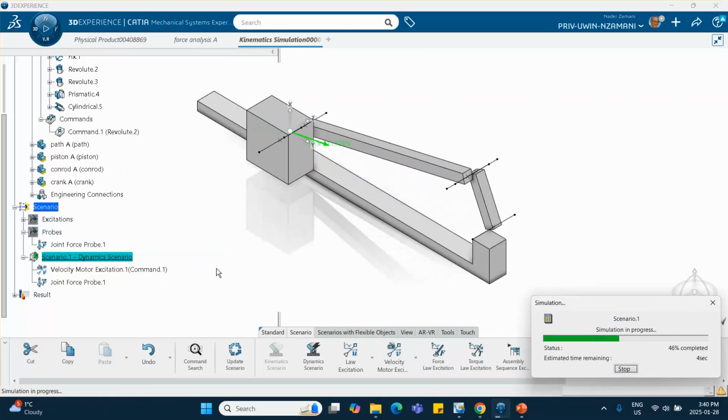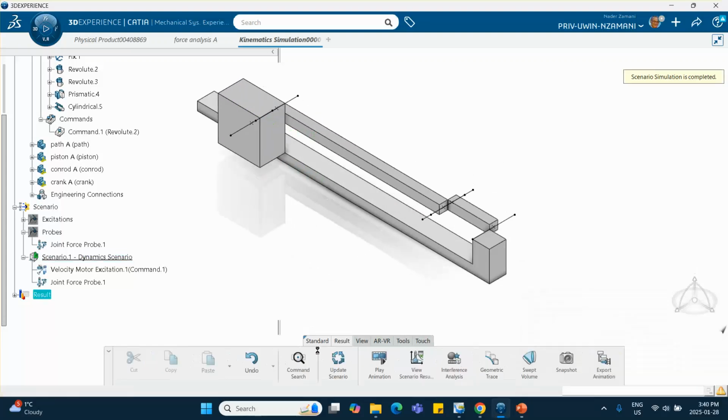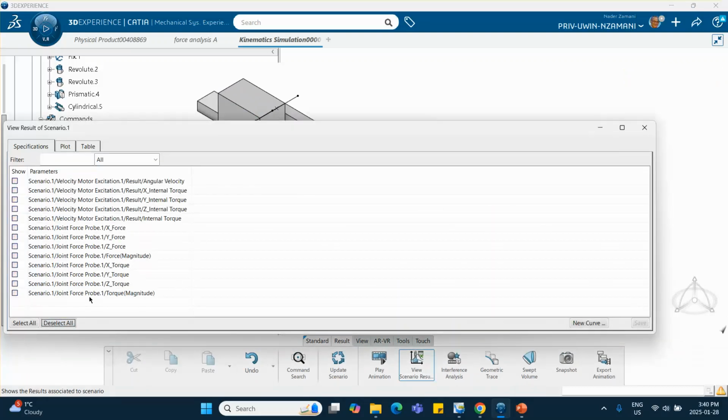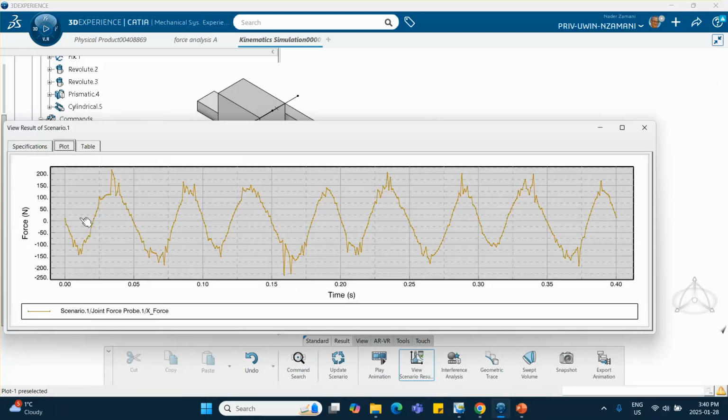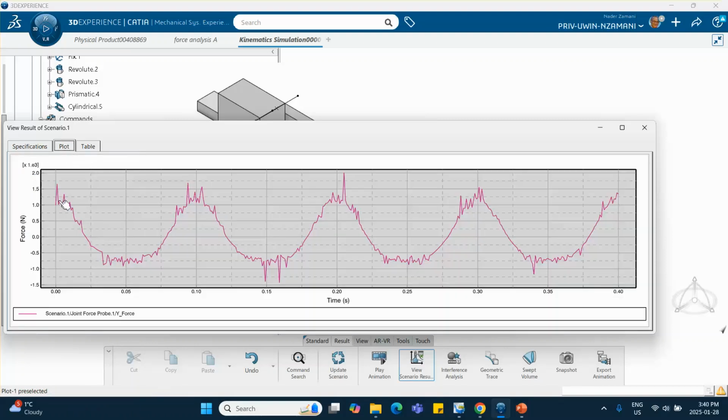This is not DASSL, it's symplectic Euler, and we're going to plot the force at that joint, same thing that we did before. Deselect all, and it was, I think it was here, X, right? Yeah. Actually, let's check the other one. Not that one. Let's try Y. Yeah, you see it goes between 1000 and roughly 590 with all these spikes in it.